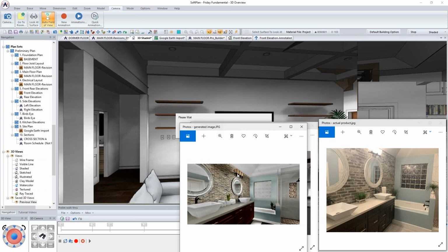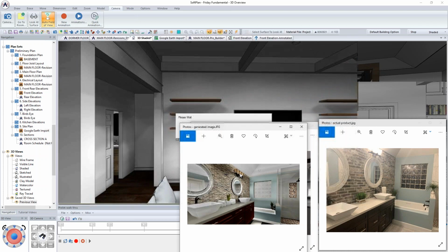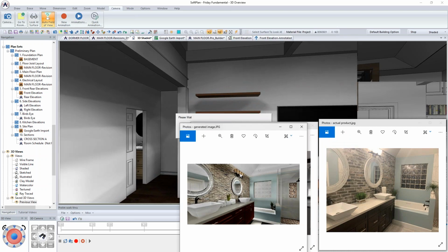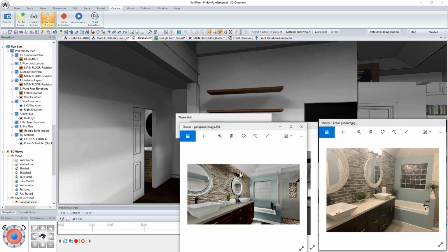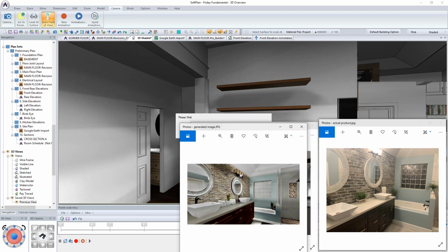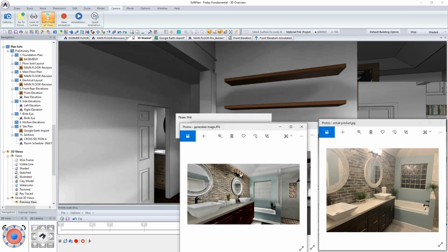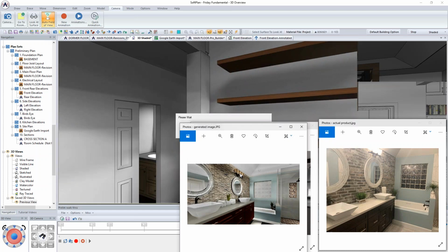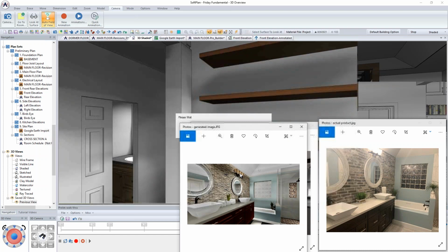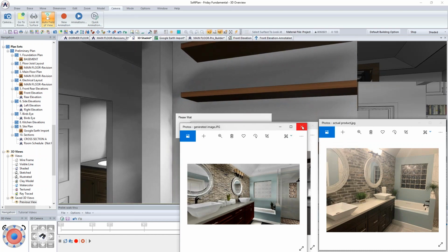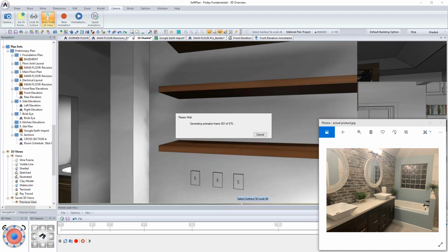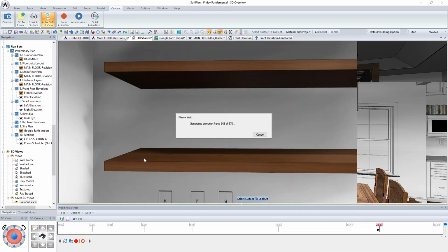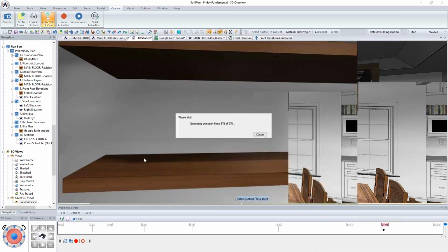Now, you can right-click and edit any light fixture that's in there. Part of the light fixture is that you can go to the light tab and set it to on. Once it's turned on, go to the custom option, and that allows you to modify the brightness, even the color of the light fixture. So if you wanted more of a yellow hue as opposed to the bright white hue that's there, that would do it for you as well. That's how you can do all of that.